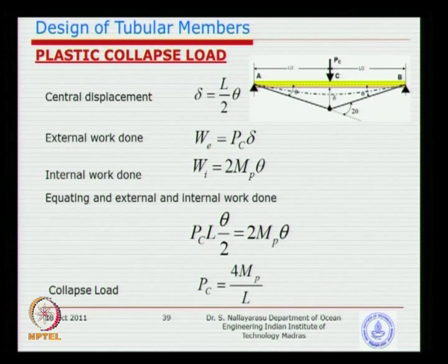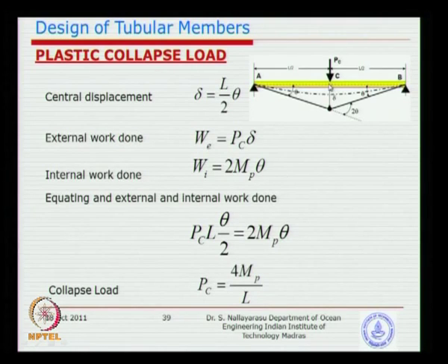So what we are achieving, just because the stress distribution changes from triangle to rectangle at the center for a small portion, is that we increase the load from My, the normal bending moment, to a plastic moment. This is similar because the bending moment diagram does not change whether it is in the elastic stage or the plastic stage. What changes is the stress diagram across the section, from triangular to rectangular.